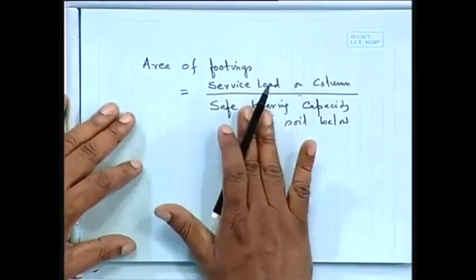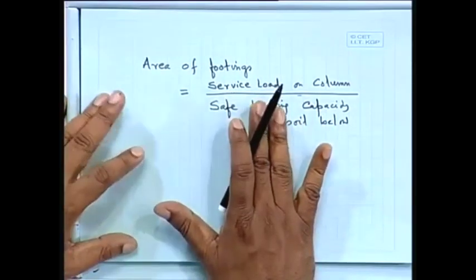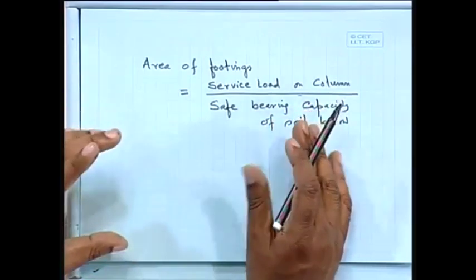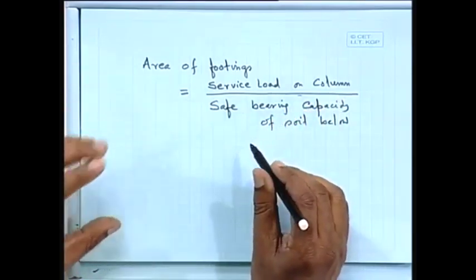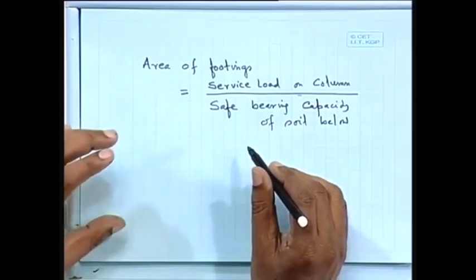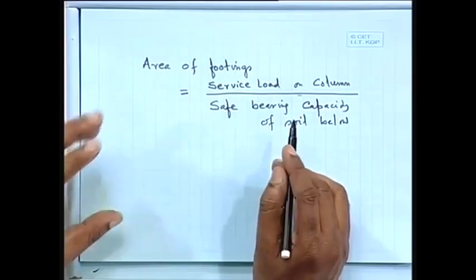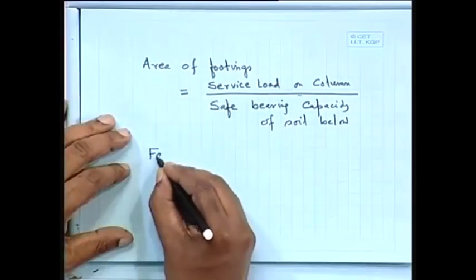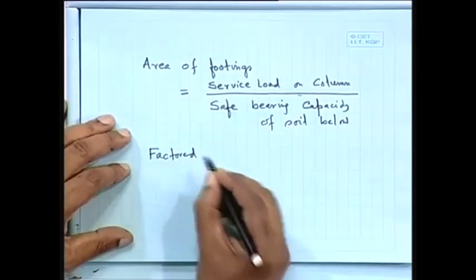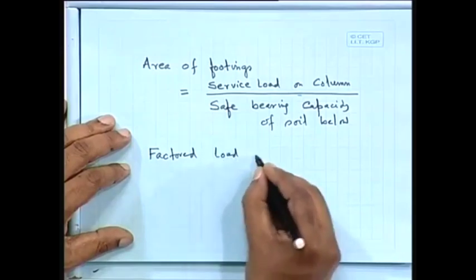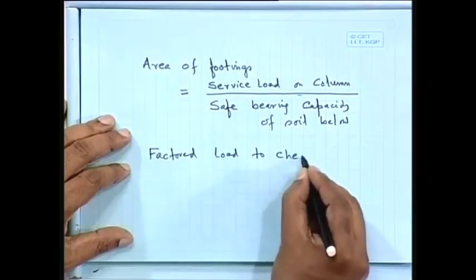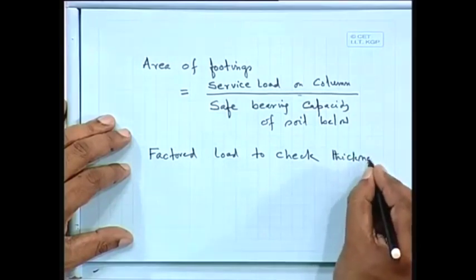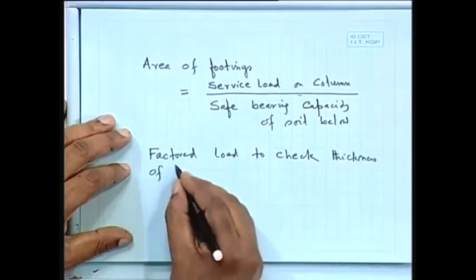Up to this you will get your service load, but now you have to give the dimension, the thickness of the footing. When you have to give the thickness of the footing, then we shall go to the factored load. So factored load to check thickness of footing.